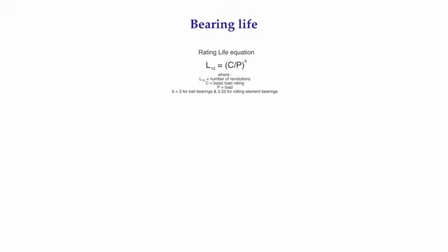The actual load that a bearing is subjected to is expressed in a rating life equation as the variable P. The L10 term is expressed in numbers of revolutions, usually in the millions, that will occur when 90% of its life is gone with just 10% of its expected life remaining. To statistically determine the life of a bearing, you take the basic load rating of a bearing, divide it by the actual load it sees, then multiply that number by itself 3 times.